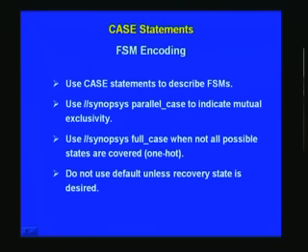And regarding writing an FSM, a finite state machine, you can use the case statement, of which we have already seen a couple of examples before, to describe basic state machines. And this also we have already seen: Synopsys parallel case to indicate mutual exclusivity, and full case when not all possible states are covered, as for instance in a one hot machine.